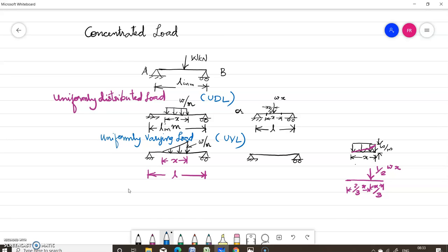So it should be noted that even in the absence of direct actions, internal forces, that is bending moments, shear force and axial forces, and support reactions can exist in a condition of static equilibrium. So the sources of such indirect static loading may be support displacements, that is due to settlement of the supports or rotational slips of the supports, or due to constructional errors, accidental eccentricities and lack of fit, and also environmental changes, that is changes due to temperature, shrinkage, and creep effects.